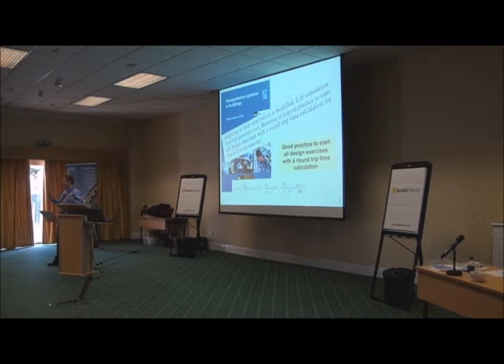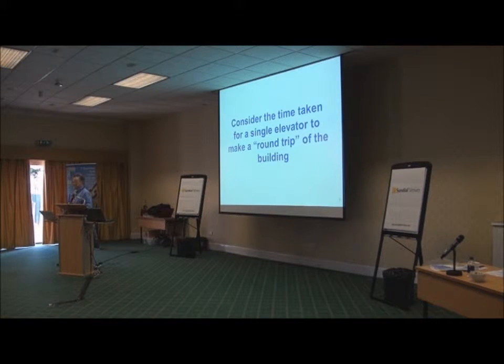Actually, most of the simulation experts in this room would agree that you should start with a round trip time calculation. Those good old-fashioned round trip time calculations. They're really robust, and we can talk about them in CIBSE Guide D, section 4. I'll give you lots of bullet points if you want to go and read that. But it is good practice. Even today, when we're talking about simulation, I'm going to start with a round trip time calculation because it's actually very relevant. And the more I do with simulation and dispatching, the more I come back to the round trip time calculation and what we can learn from it. So it's an important thing.